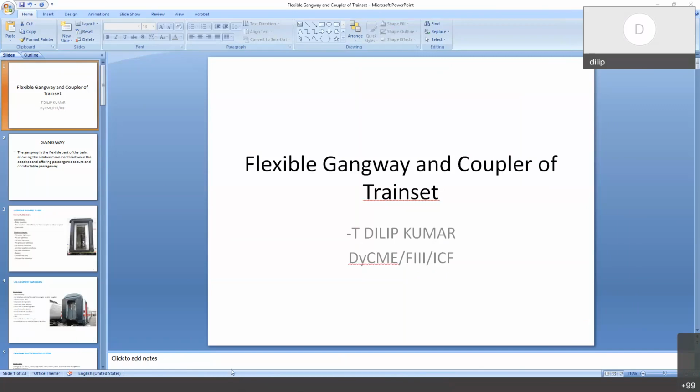Sir, can you attach one loco and clear the section in case of an emergency? See, actually, I forgot saying, the complete train, between coaches, this is a semi-permanent coupler, but at both the driving ends, it is a normal CBC coupler, and the coupler height is 1105 mm. So the complete train as such can be moved in case of emergency.